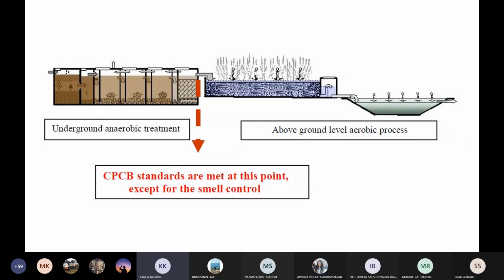So now the first thing is your underground anaerobic treatment. In your underground anaerobic treatment, what happens is your settling tank is there, which is 80% of the capacity. Then comes your constructed wetlands, which is in purplish color here, which is nothing but your reeds bed. Can you see that the overflow from your settling tank is overflowing into your reeds bed? Then the reeds bed will have baffle walls, and then the plantation is there, and that plantation absorbs the sludge. So by the time it comes into your collection tank, on the right hand side, it then overflows into an oxidation pond, which is your green.